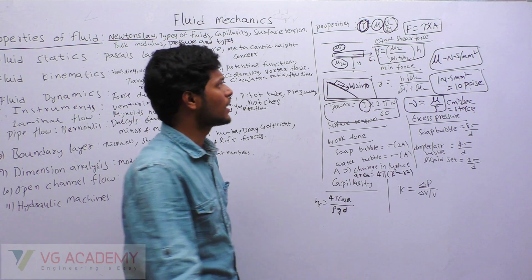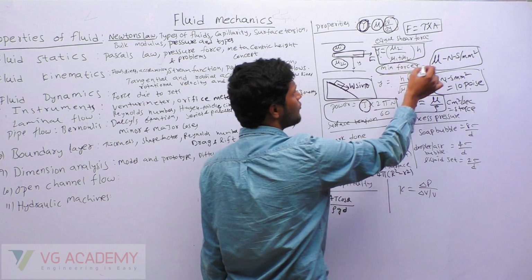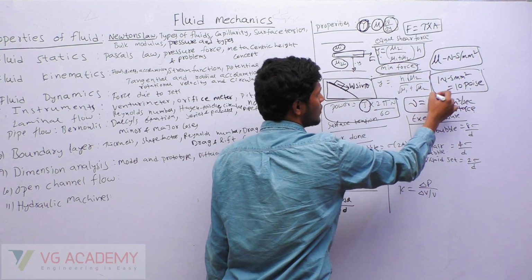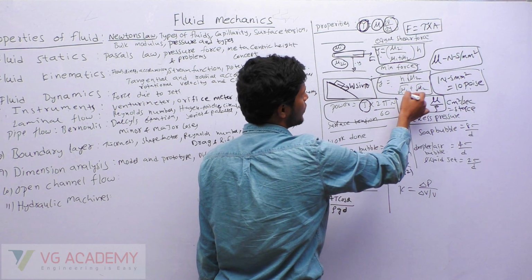Okay, next, suppose you want to have the minimum force. To have the minimum force, what should y be? It is h into root mu2 divided by root mu1 plus root mu2.